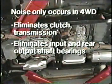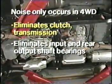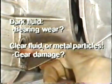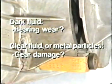If the noise only occurs in four-wheel drive, that eliminates the clutch and transmission, as well as the input and rear output shaft bearings. A bearing problem may leave signs of its failure in the fluid. If the fluid is clear, the problem is probably not a bearing, but more likely a gear.